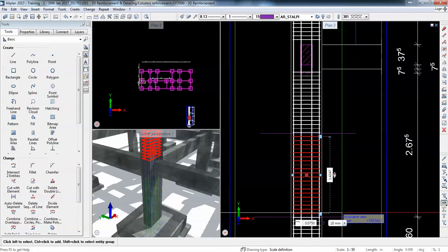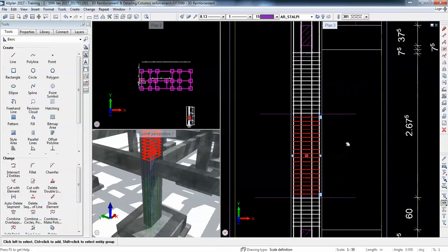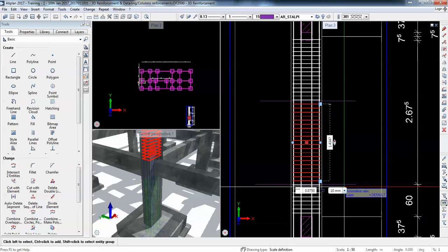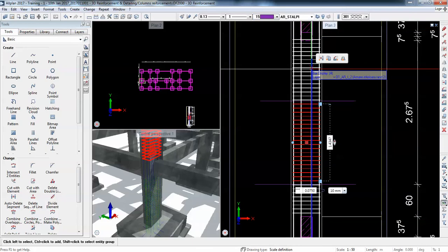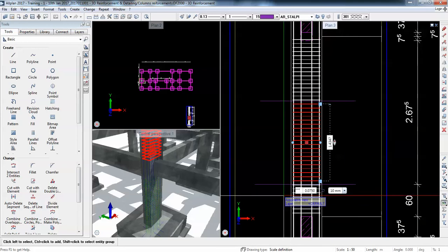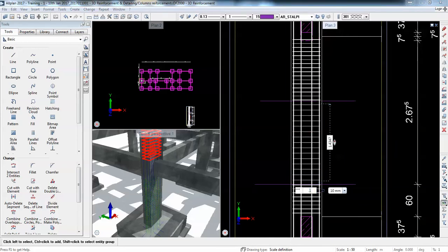Also, you have the possibility of changing the diameter, and by doing so, you will get new marks. So this is one thing you can consider. Changing the diameter is the fastest way of getting new rebar marks for any placing of a bar. You can do this trick for stirrups, but also for longitudinal rebars. But for longitudinal rebars, you can do any of these changes in a section where we see them placed. So 0.5 here as well.